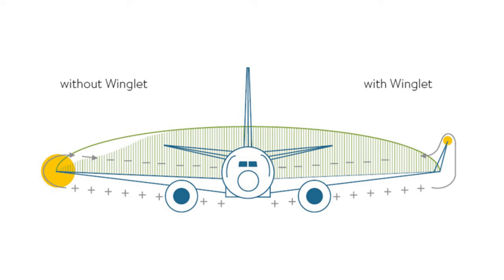This local drop in effective angle of attack near the wingtip due to the wingtip vortex also decreases the overall lift of the wing, which is another reason why we want to minimize the effect of the circulation gathering around the wingtip as a result of lift generation.